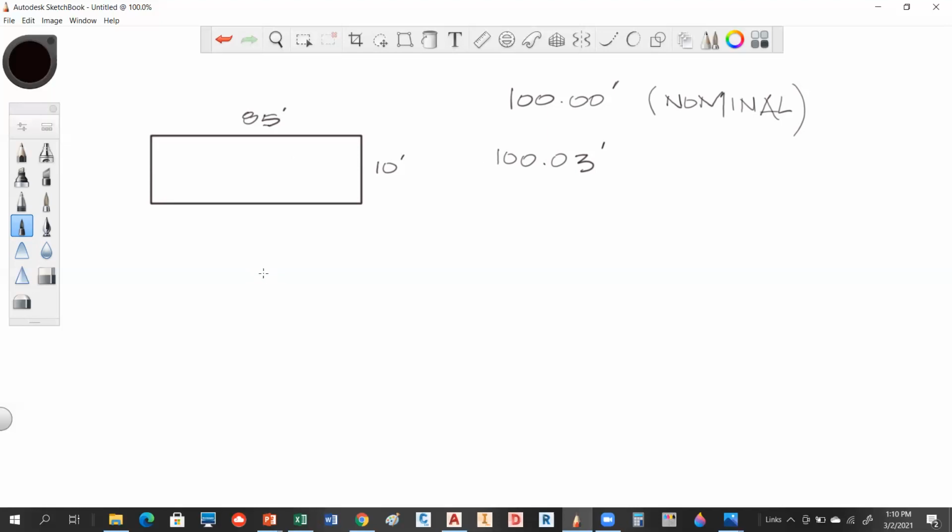Okay. So if you go back to the notes that we looked at last week, we said that the incorrect length is L minus L prime divided by L prime. And that gives me the amount of change per foot. And you have to recognize, if you remember, that L in that equation, little l, is the true distance. And L prime is your nominal distance.